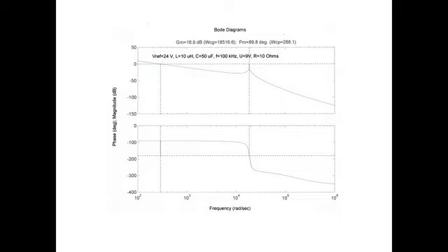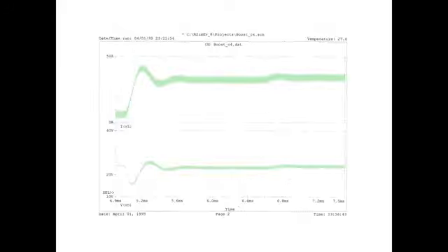And so let's look at some load step responses. Okay, so what we do is we have the closed loop control, and then we flip the load, and we see how the voltage and current respond. In this case, we're stepping down the resistance to see a load step from light load to heavy load, and then from heavy load to light load. Okay, so here's one from one input end to the other, and we can see that here's the voltage response, and here's the current response here, and it pretty much settles out. I think this is a simulation thing out here.